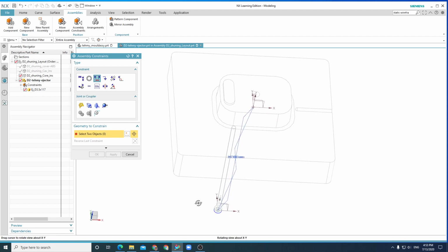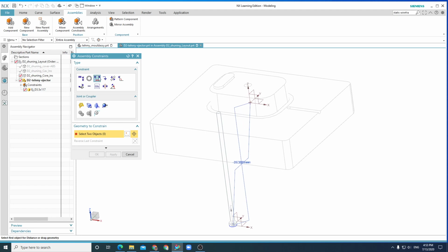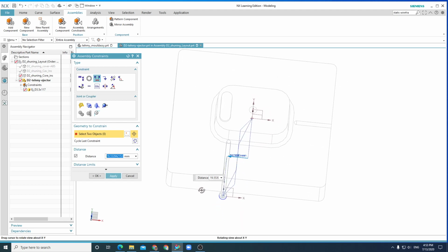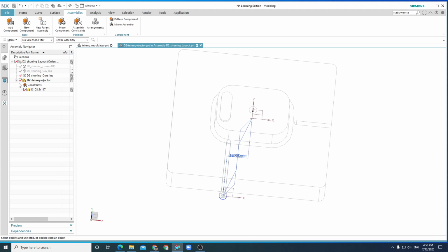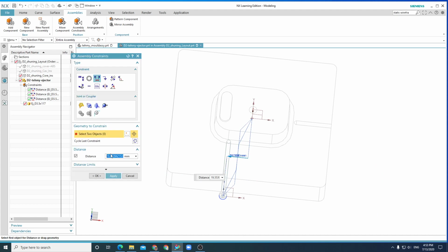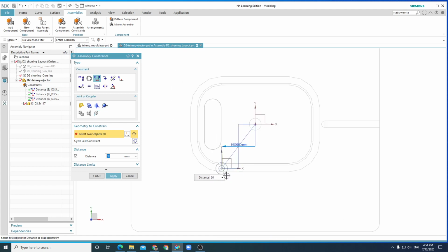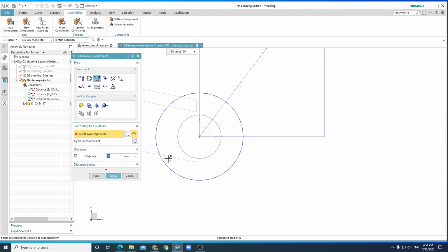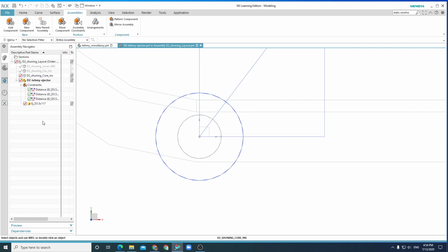So next we will do the dimension, all right, of this datum to this datum. All right, so it will determine the x direction. Okay, we can give it again. I think I recorded already, so lost it. So double click, come over here, double click on the last one, right? So I try to put it to 20. See how it goes. So let us zoom in, have a look, see how it goes. All right, so yeah, I'm almost at the edge here, so that's where I want. Okay, so all of you decide on which location that is going to be.